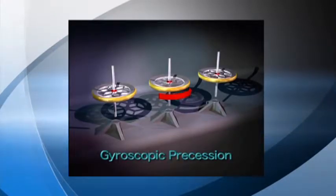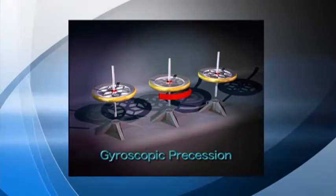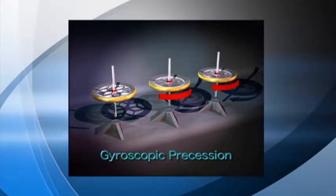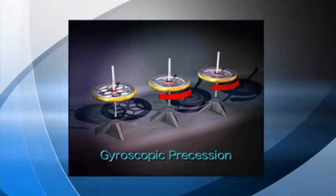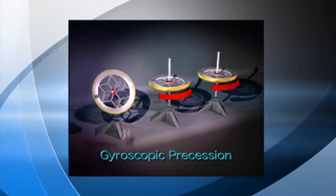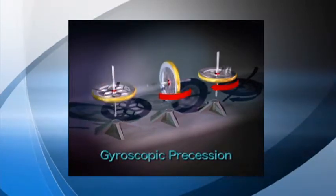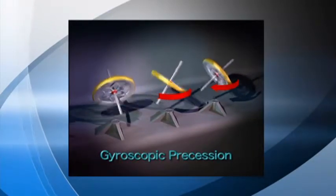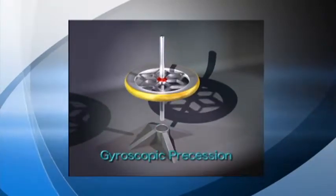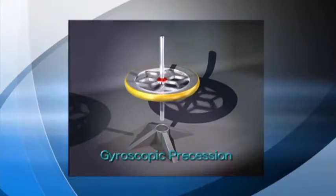Now, the second principle is called gyroscopic precession. Precession says that a force applied to a spinning gyroscope will produce a resultant force which is 90 degrees ahead of the plane of rotation and in the same direction of the initial force. Let's take a look at how that works in the next slide here. First of all, we can see that this gyroscope is rotating in this direction as shown.